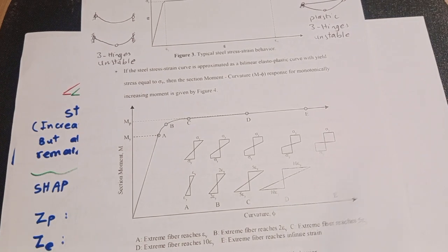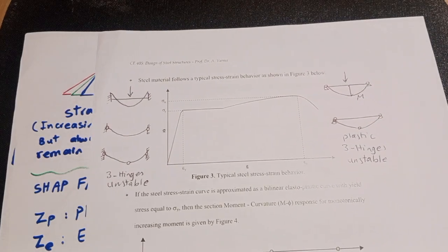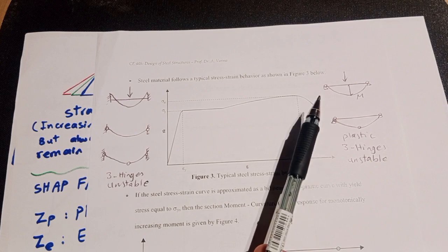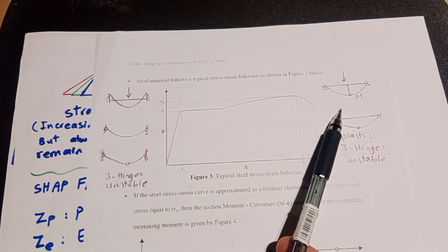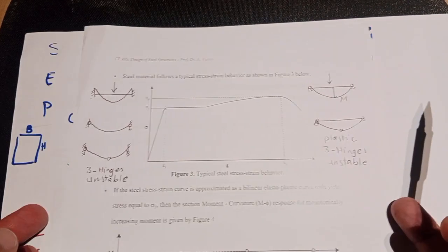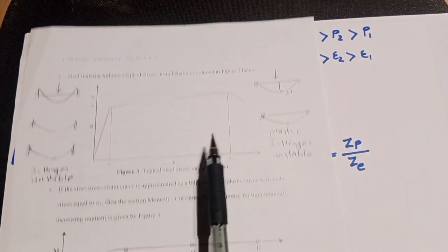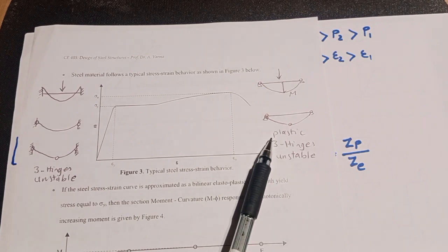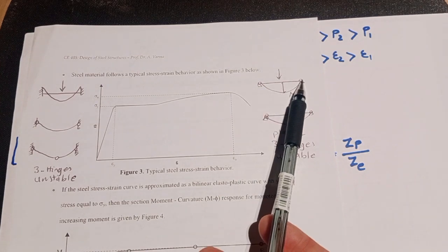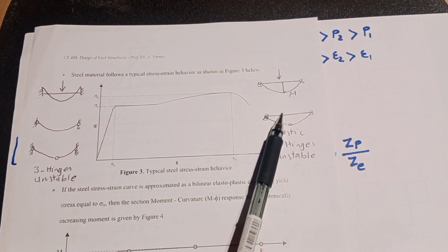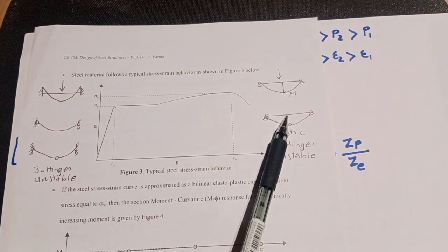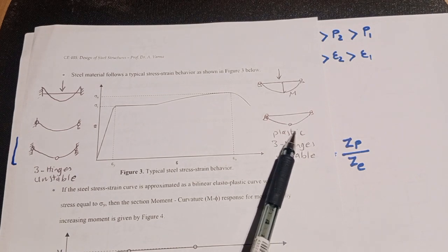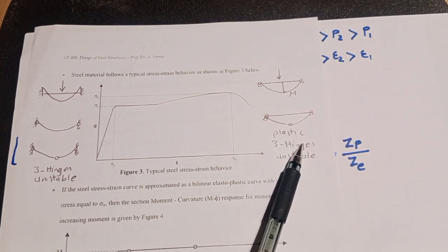This is the section view, and if we want to see it in the superstructure view, or beam view, for example, I've chosen a simple restraint on the beam. If we have a simply supported beam under load, and the load is increasing until the maximum bending moment point reaches plastic, it becomes a hinge.